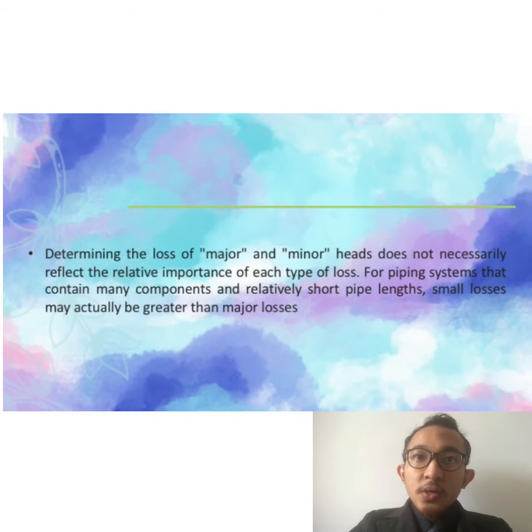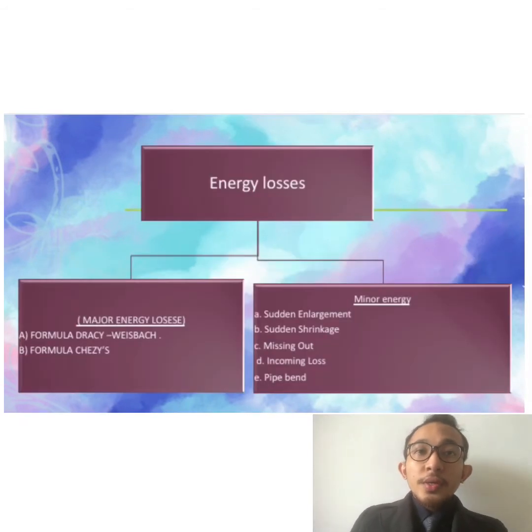Head loss does not necessarily reflect the relative importance of each type of loss. For piping systems that contain many components and relatively short pipe lengths, minor loss may actually be greater than major loss.